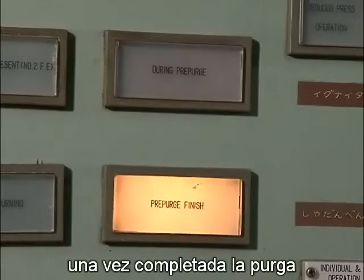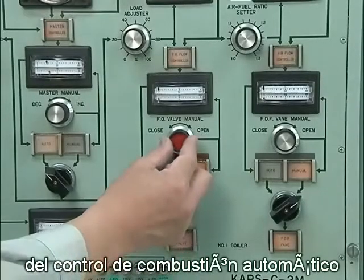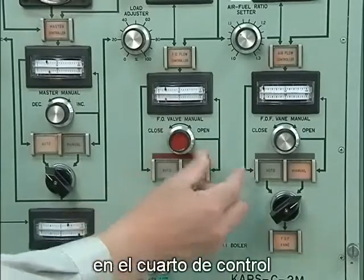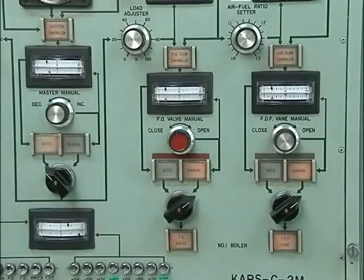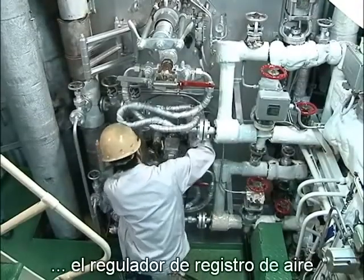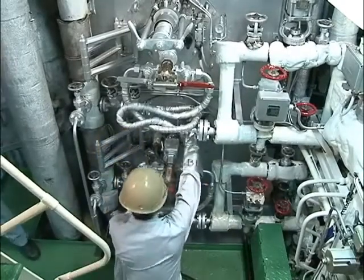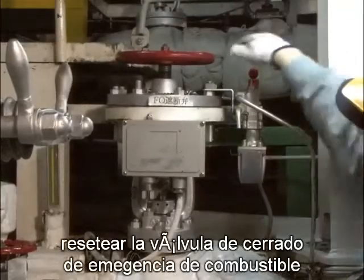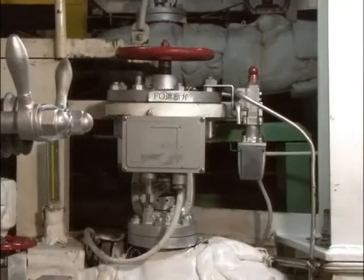Upon completion of pre-purge, set fuel and air control output signals of the automatic combustion control, ACC, in the control room to those at the time of ignition. In front of the burner, fully shut the air register damper to prevent flame from being blown out at time of ignition. Reset fuel oil emergency shutoff valve and open fuel oil line valves and cocks.